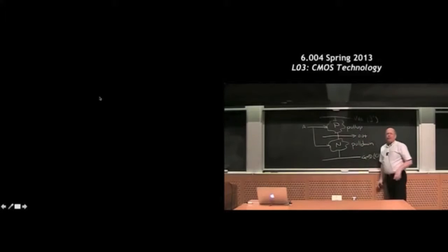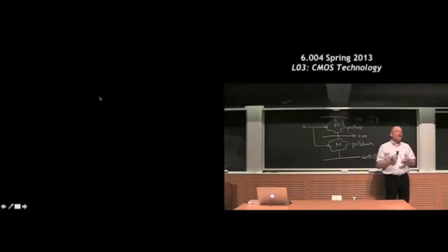Why do we call them pull-up and pull-down? I mean, they're very appropriately named. So what happens is if I close enough of the voltage-controlled switches up here, what will I end up doing? If I can make a conducting path between the output node and VDD, what will happen to the output node? It gets pulled up, as the voltage gets pulled up until the power supply rail. In other words, if there's a conducting path of these voltage-controlled switches that connects this node and this node together, this node will get charged up by the power supply.